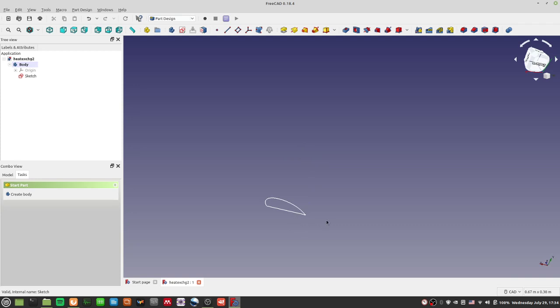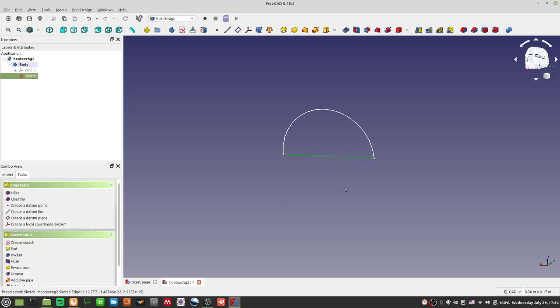Okay, next thing you want to do is this thing called revolution. Now, we spent lots of time talking about drawing a line, and now we draw the semicircle. Now at least we got our foundation covered, so that makes drawing the semicircle very easy. So next thing I want to do is to revolve, and it's got to revolve around some point. I actually want to revolve it around this line here.